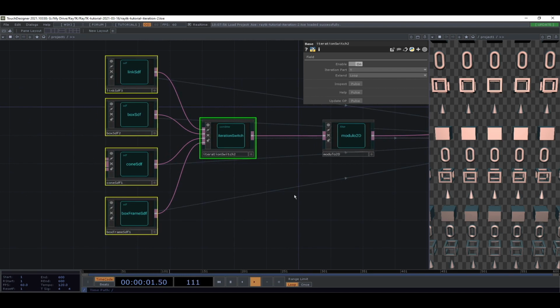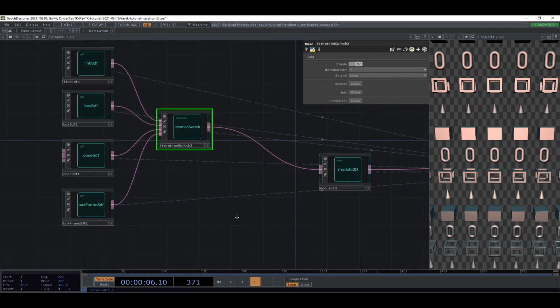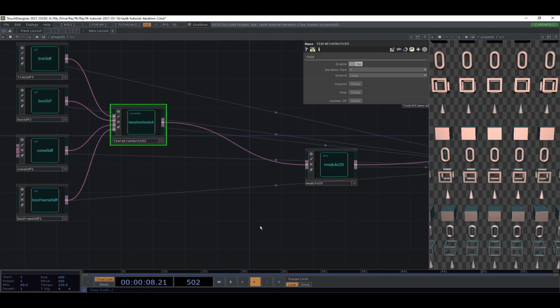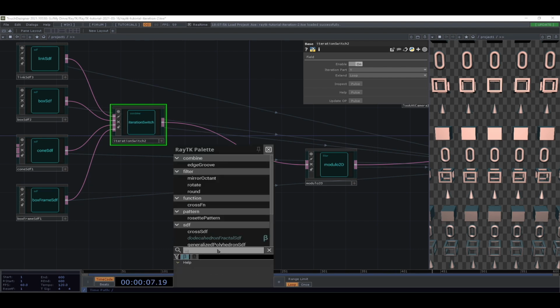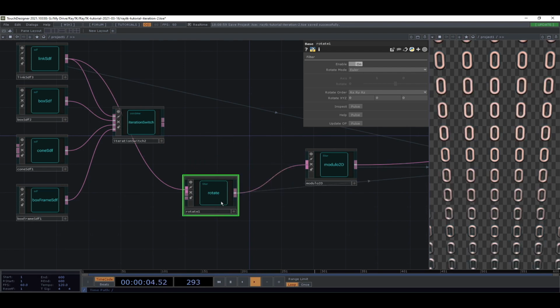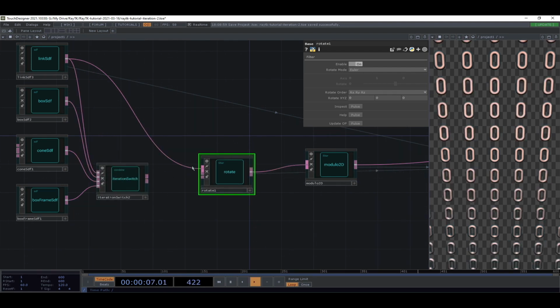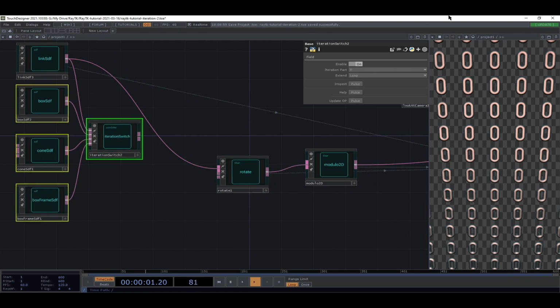If we are working with other operators like iteration field, you can actually make use of both parts at the same time. Now, similar to what we did before, I'm going to create a rotate, and we're going to put that between just that first link and the modulo here, so it's no longer going to be using the switch to repeat those, and we can actually just get rid of those since we don't need them anymore.